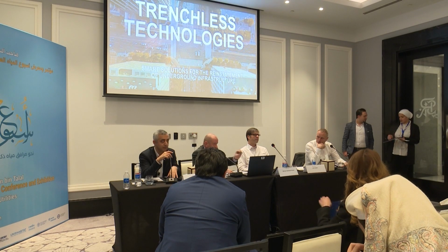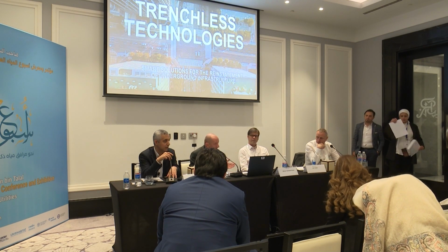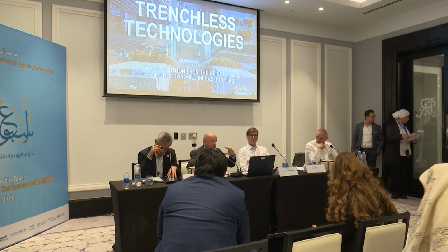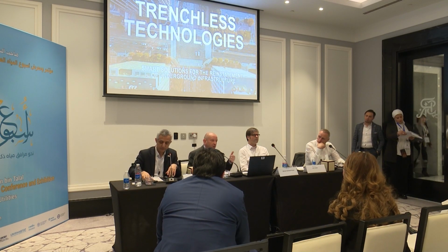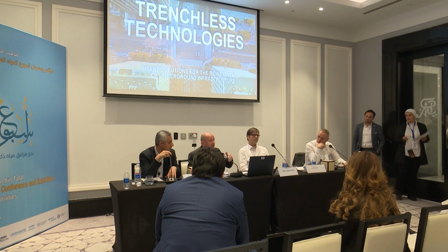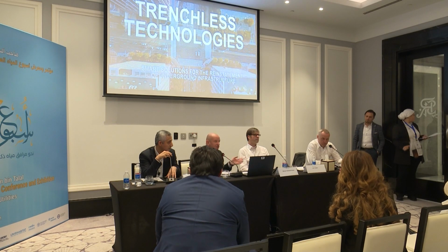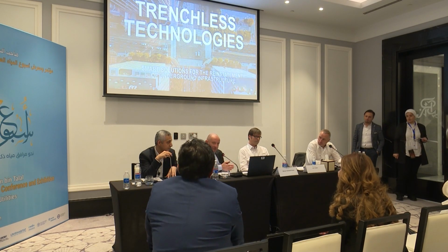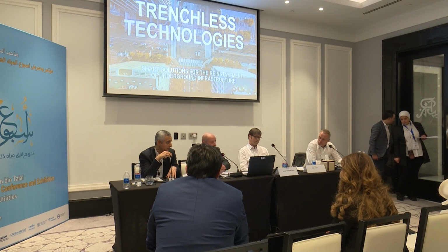Just to answer part of your question briefly, the limits in CIPP lining are the size, the no bends, and at one point we are limited with what shape we can do, which makes sense. So if it is too late, it's simply too late. Most important is to have trained crews on the site because the material is half ready, as you have seen. And this is something where we more and more survey that we have trained individuals, not just a trained company, and they change the people, so that the individuals are trained and know what they do, because they bring the good quality into the new pipe.